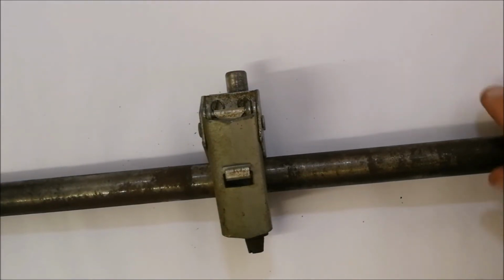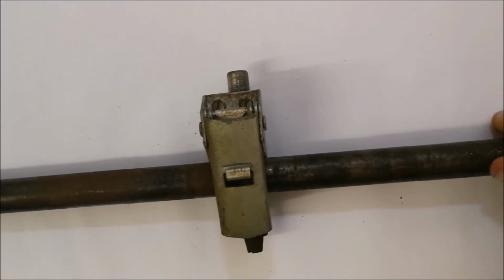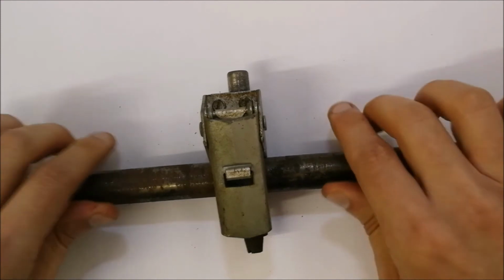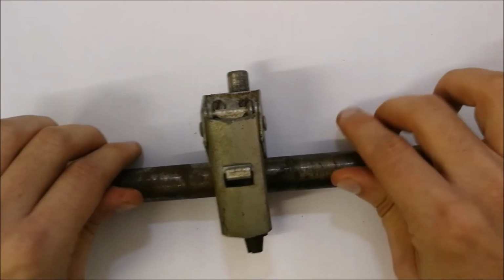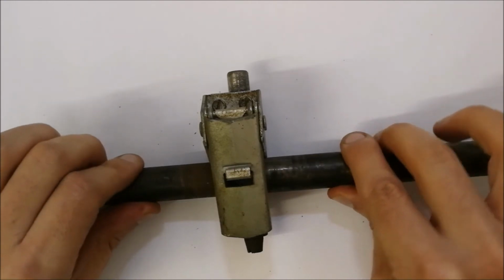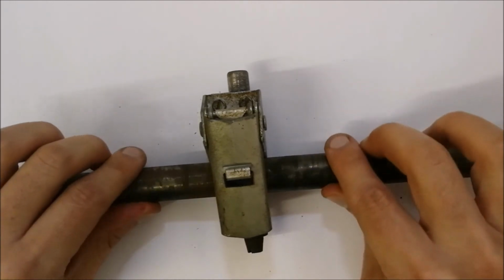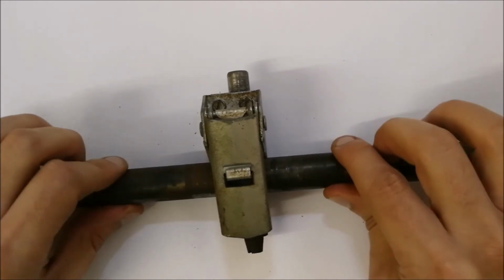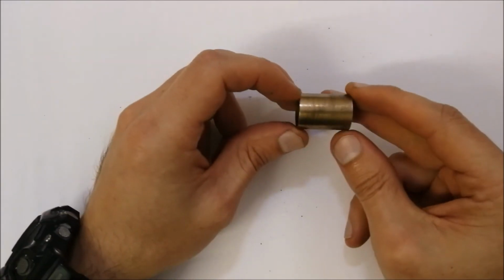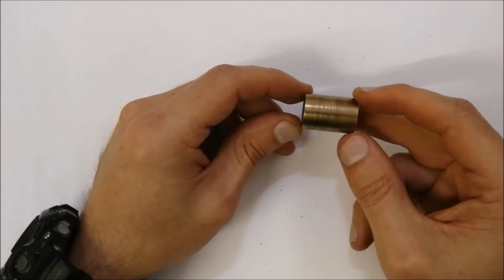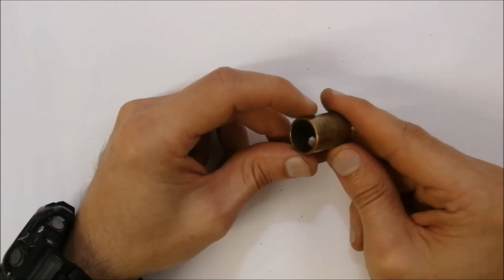But if you have a look at this specific shaft, to turn it is quite difficult. It's not too difficult, but it takes a little bit of force to turn it. And often that little bit of force is critical. You need to make it turn much more easily, and for that reason bearings will be used. Something else to keep in mind is that sometimes these bushes can also be made out of Teflon.